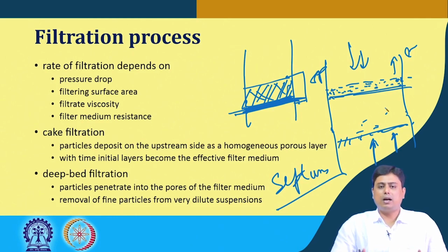We are handling solid particles, and logically cake filtration is the process by which we recover the solids. In our case, solids are the more valuable product. So, we will stick to cake filtration in the next set of slides and classes. Here we can recover the solid particles as the cake or porous media.